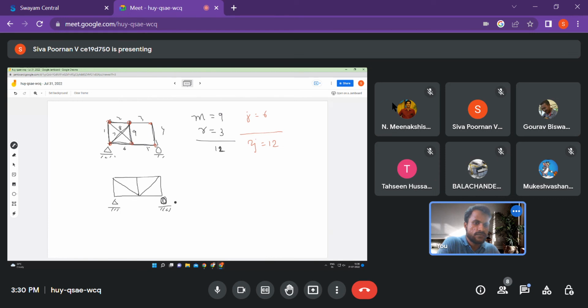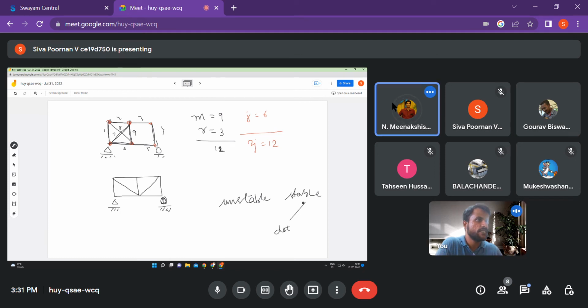So only when we have a structure that is statically stable, can we say that it is statically determinate or indeterminate. So if I have to put it as a flow chart, I can say that we have unstable structures and we can have stable structures. Under stable structures only we can have determinate and indeterminate. So once we say that a structure is statically determinate, then we definitely mean that it is stable, right? So that is why we should not call this a determinate structure, because it's unstable. First of all, we need to check whether it is stable. Then only we can say whether it is determinate or indeterminate, right? So you are right that it is not considering stability, but I'm trying to understand what we did wrong that it is not considering stability, or in other words, what should we do so that we can consider stability?